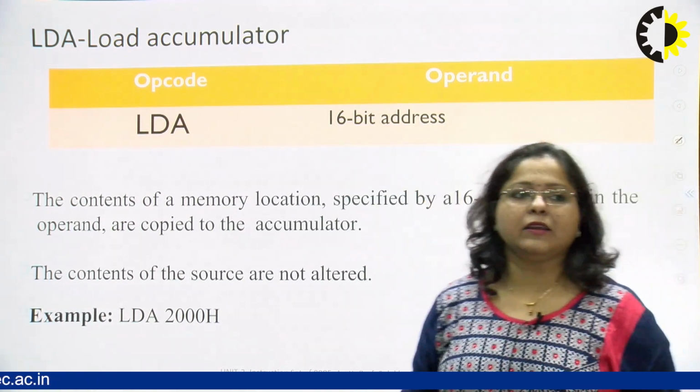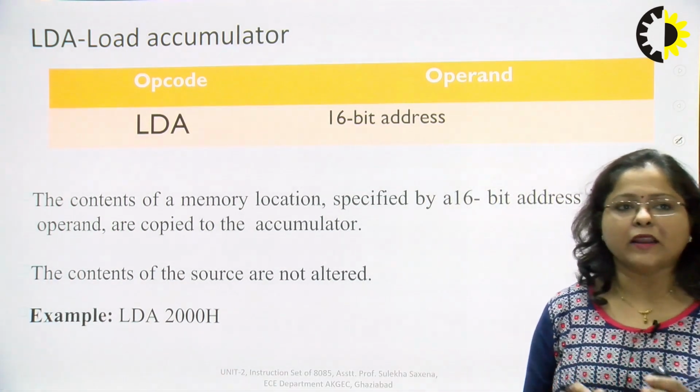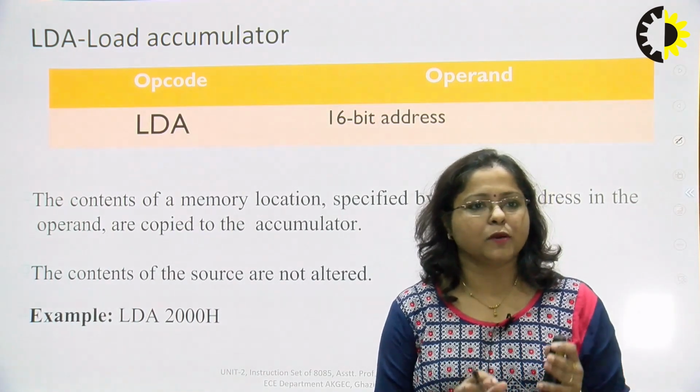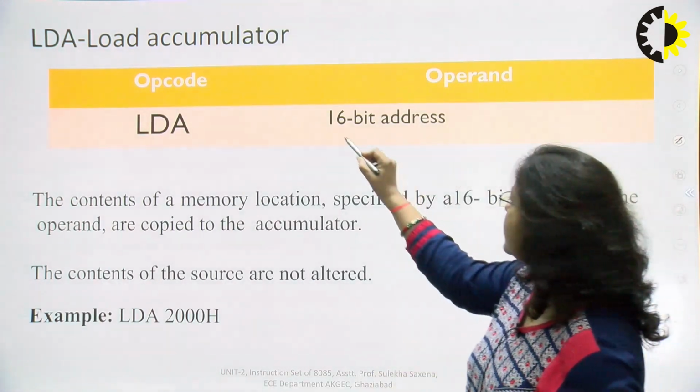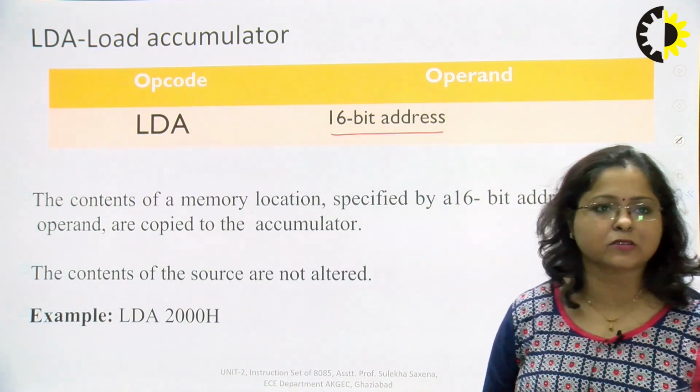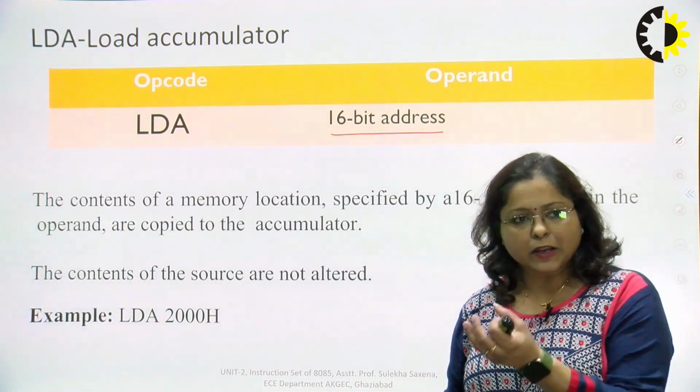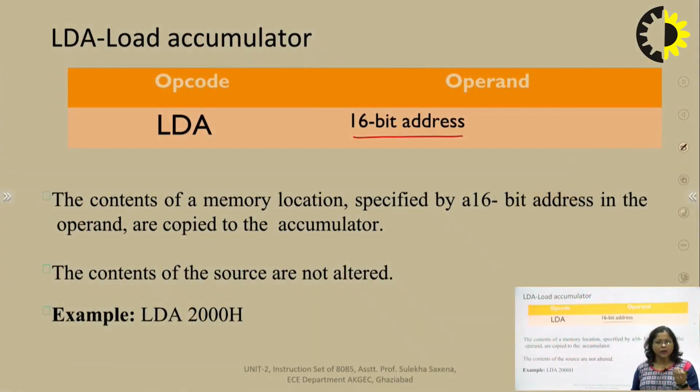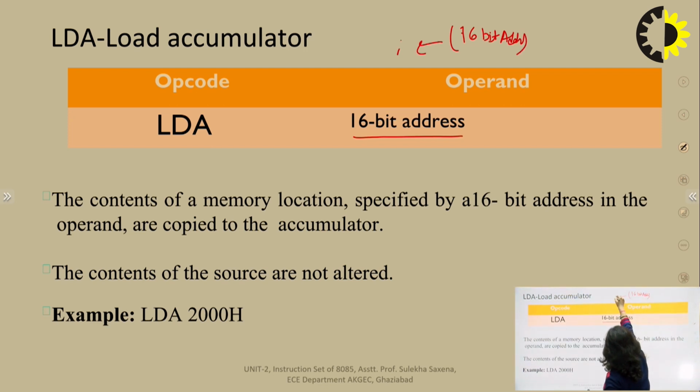Next is LDA, load accumulator directly with the content of memory address. So here a 16-bit address is directly specified in the instruction. The data is read from this address and copied to accumulator. As the address is directly given in the instruction, this instruction is of direct addressing mode.